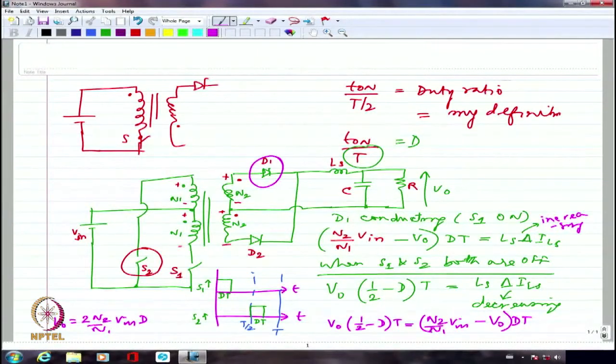And if it is a 15 volts circuit, you have to rate it for 30 volts as a factor of safety, right? That is not much really, because unless you go beyond kilovolts, the cost does not increase tremendously. Only when you go beyond kilovolts level, the cost increases tremendously. The currents or the overall power rating increases the cost quite a bit.